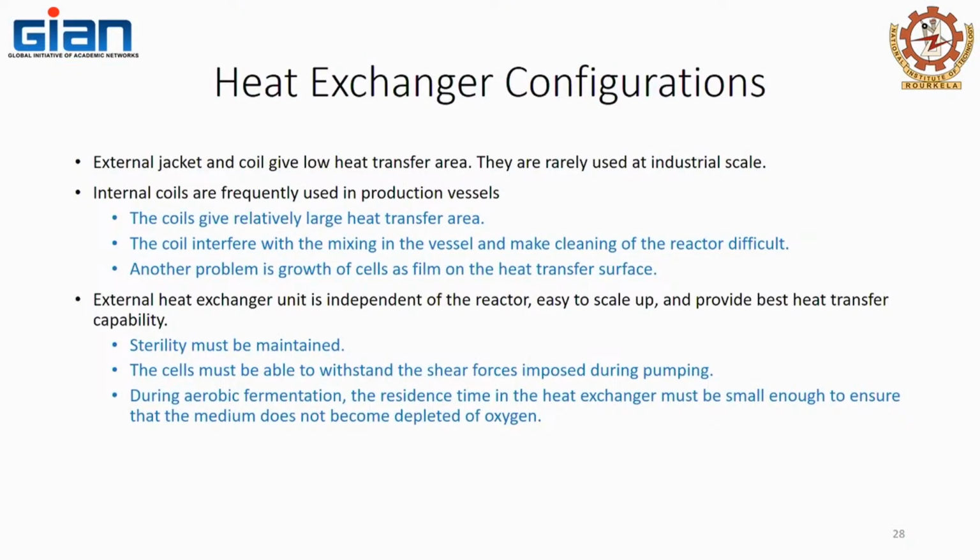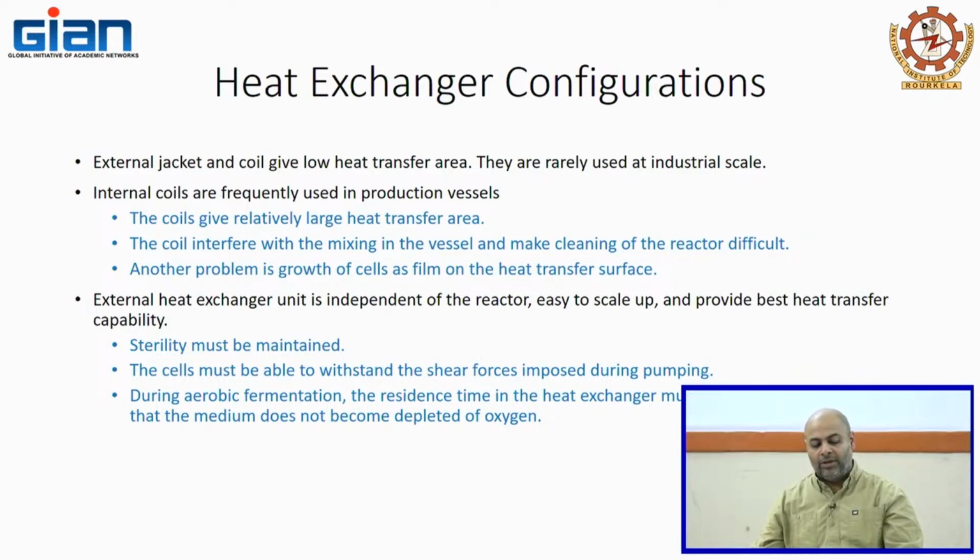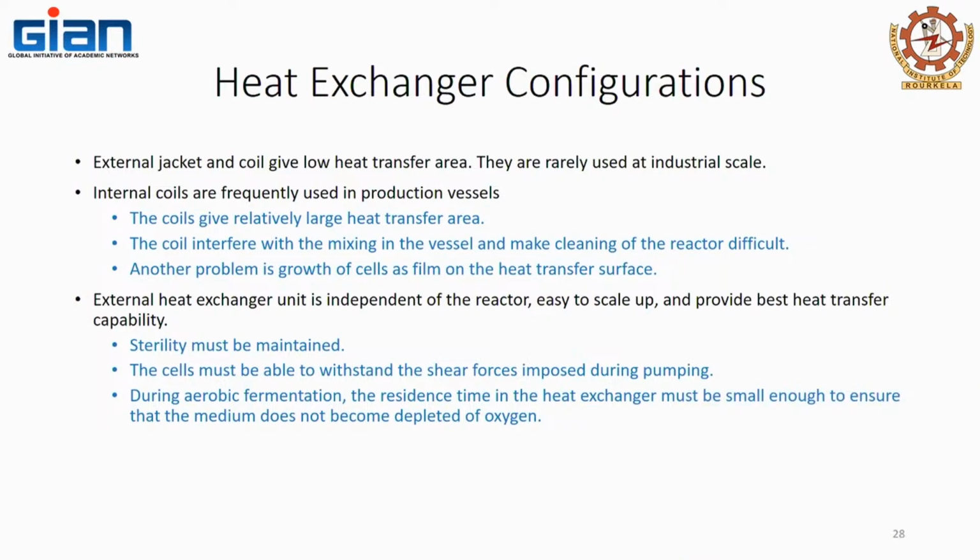An external heat exchanger unit is independent of the reactor, easy to scale up, and provides the best heat transfer capability. Sterility must be maintained. The cells must be able to withstand the shear forces imposed during pumping. During aerobic fermentation, the residence time in the heat exchanger must be small enough to ensure that the medium does not become depleted of oxygen. If you are using an external heat exchanger, you want to make sure that the medium does not get depleted of oxygen.